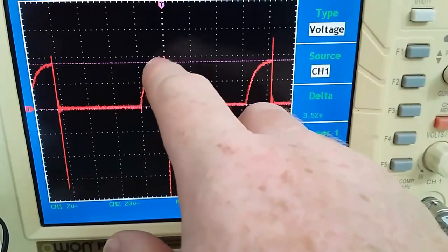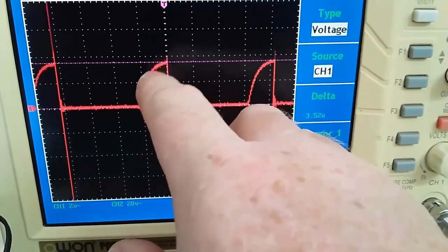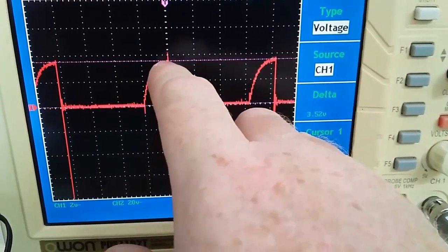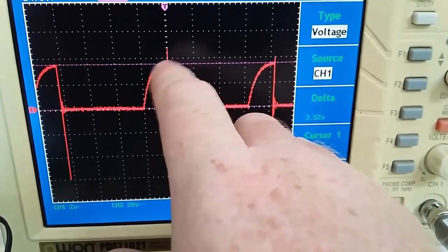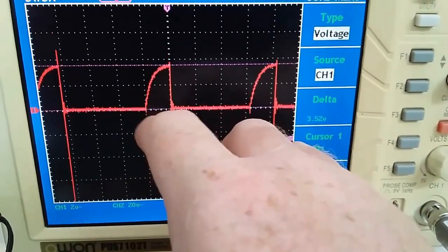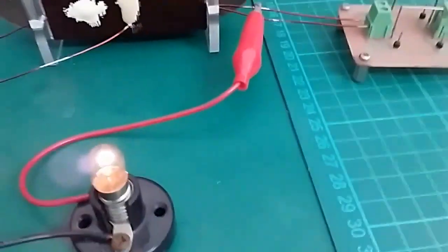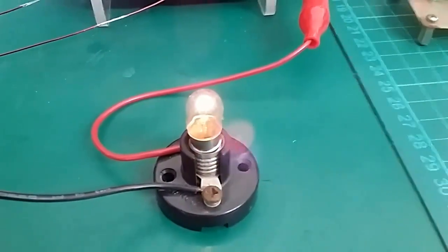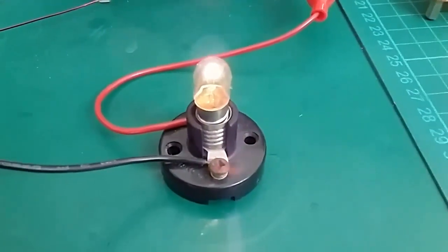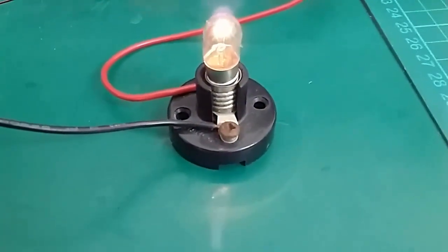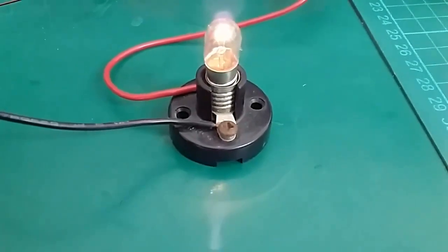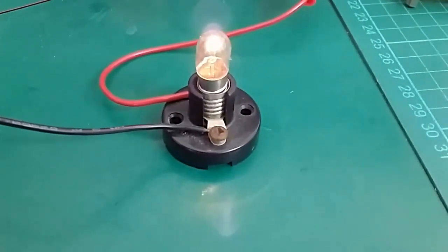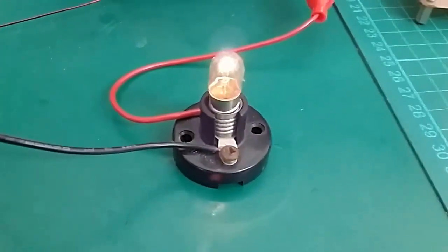So the magnetic field is much larger, and yes, it's going to cost us a little bit more, but we've got to realize that this curve here is what gets the voltage up on the coils, and you can see a big difference in the light for effectively the same frequency. With this setup, we're back up to 24% duty cycle at 2.4 kilohertz.